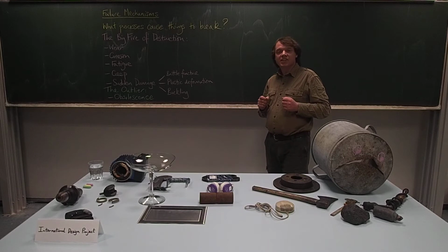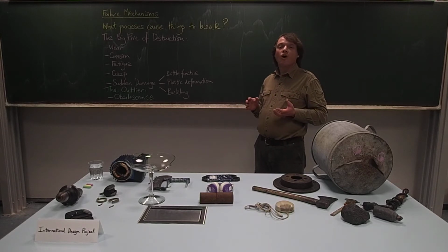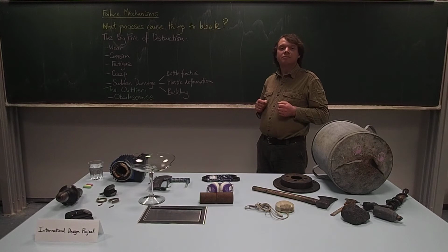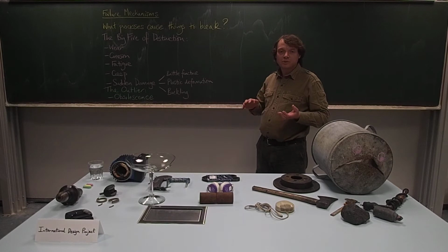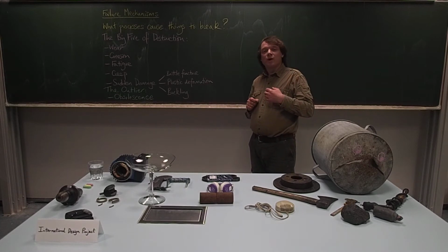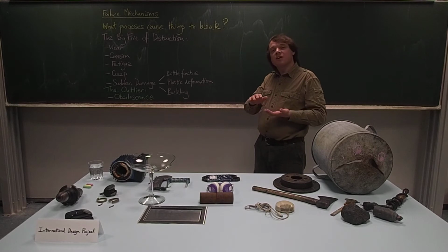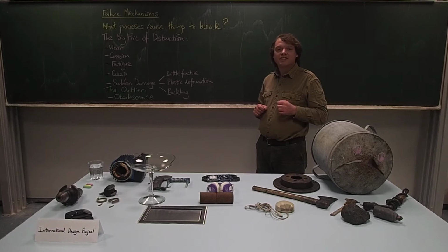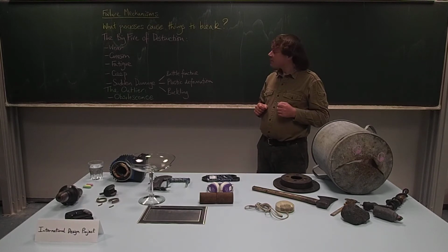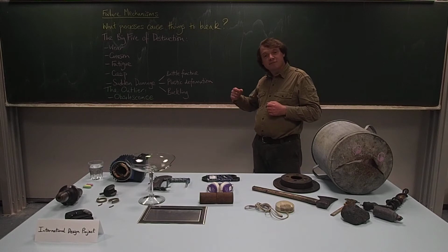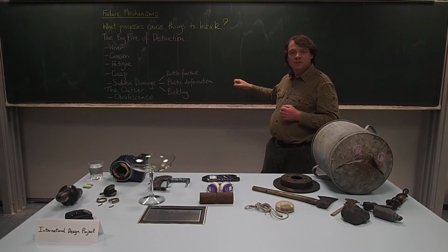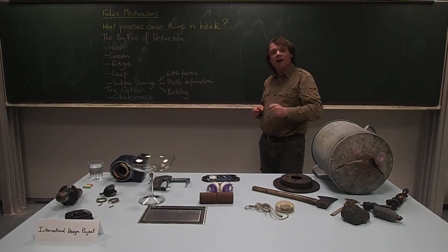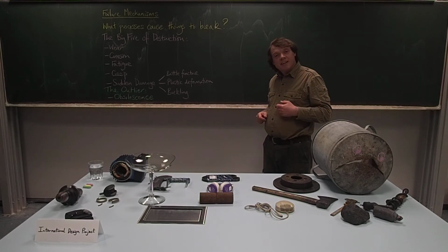Wear is essentially the mechanical removal of the surface layer of material. So the surface layer of material gets turned into a powder or smeared into a different place. Usually when you're talking about a crumbling action where you get small neat particles broken off the surface, that would be known as abrasive wear. That's essentially what you get when you take a stick of chalk and pull it down the blackboard. You get the powder left behind, stuck to the surface of the blackboard, and you can shake off the powder. You can see that it's still loose.